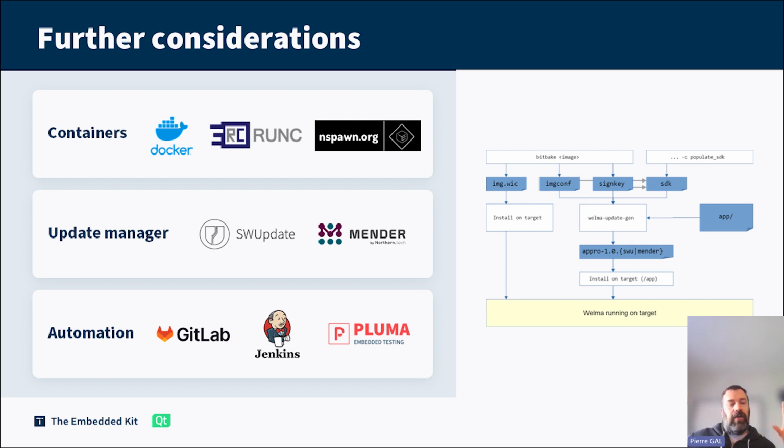So till now, we have assumed that you take your binary, you put it inside your application, inside your Yocto, and at the end, it runs as a standard application inside your system. But there exist functionalities of containerization of applications that now can be very easily implemented on an embedded system. If a few years ago, this container approach was really dedicated to server and PC, now you can enable containers on an embedded system quite easily. A lot of different technologies, Docker, RunC, systemd-nspawn, all have added value and also bring some constraints.